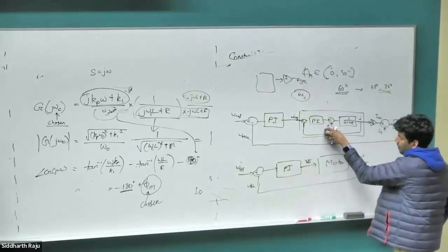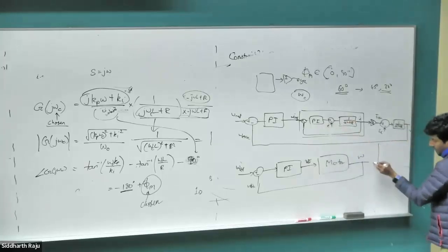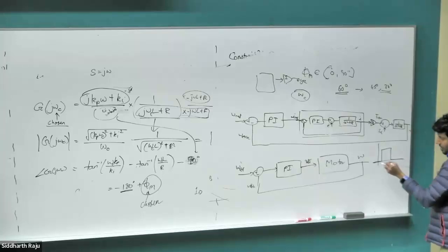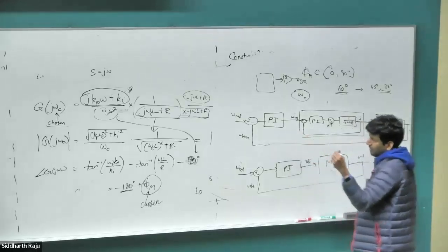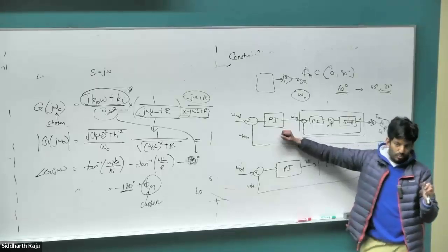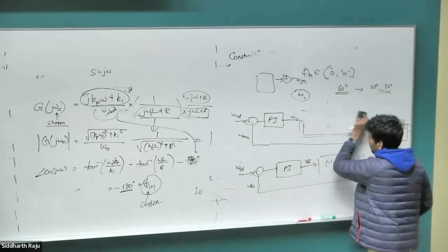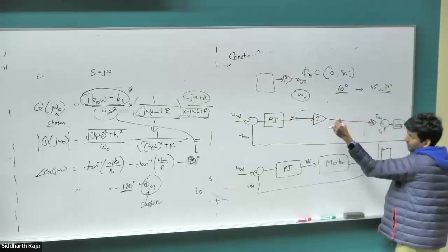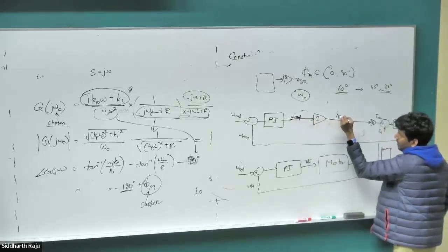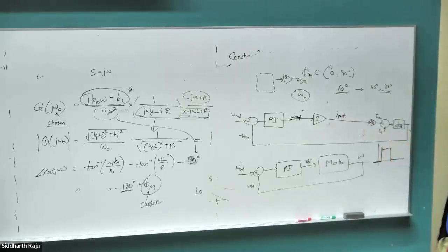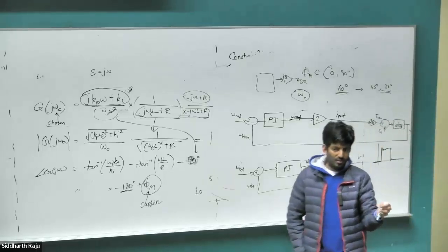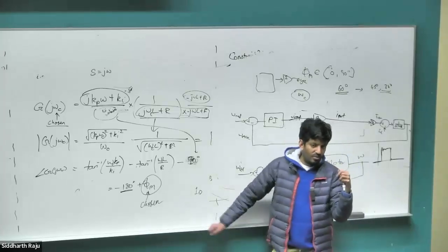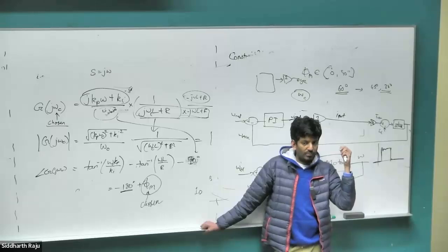Now, if my PI controller, this whole system, is operating very, very fast, right? If I apply a step and the system reaches that step quite fast, such that the outer speed controller does not even see that happen, because the outer speed system is happening at a much, much slower time rate, this whole thing can be modeled equivalently as a unity gain block, as far as my outer controller's i actual matters. Right? Because all of these fluctuations going on in an electrical system are not going to affect a mechanical system at all, because the mechanical time constant, J by B, is very large. That's the same thing that we used when we did parameter estimation, right?